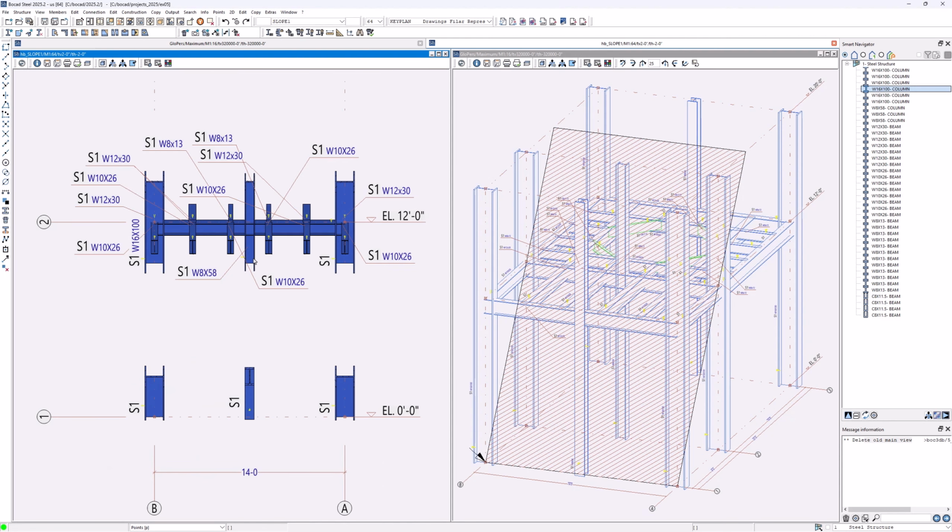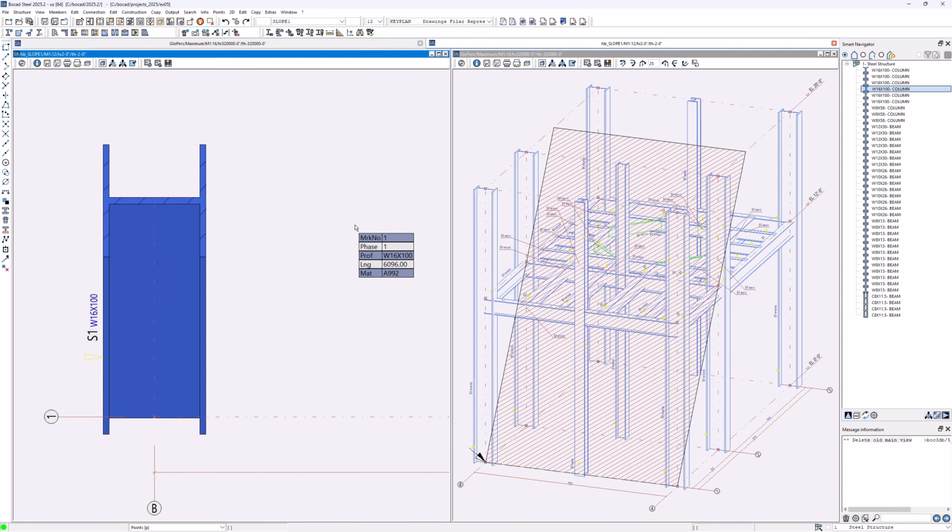Enter. The view will become a lot smaller, and in regards to the view, the text looks bigger. The text has not grown, it's just that the view is a lot smaller now, so the text just looks bigger next to it. If I change to another scale, for example this one, pick the view, we see the view has completely blown up, become a lot bigger, but the text has not changed in size.